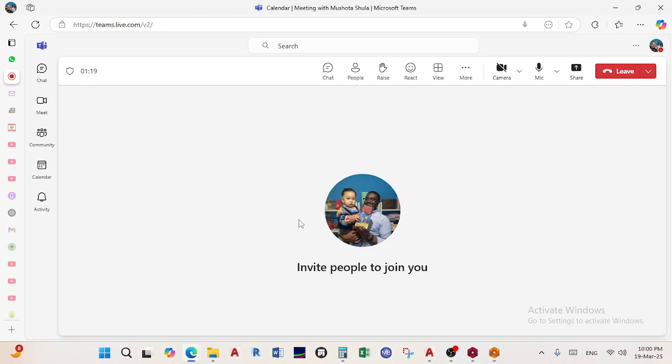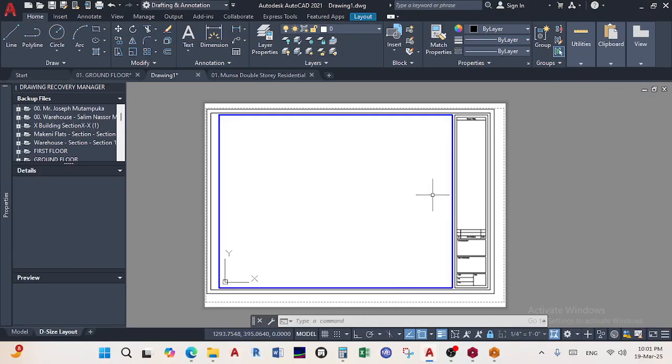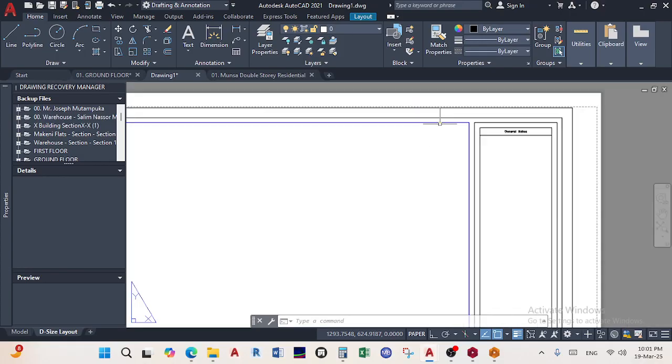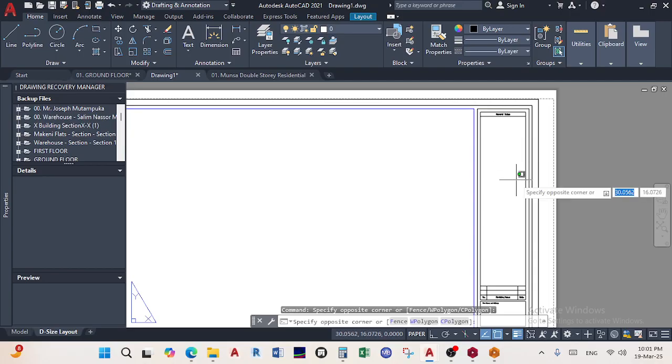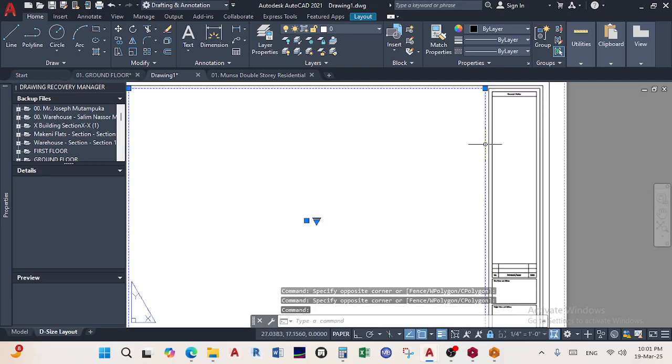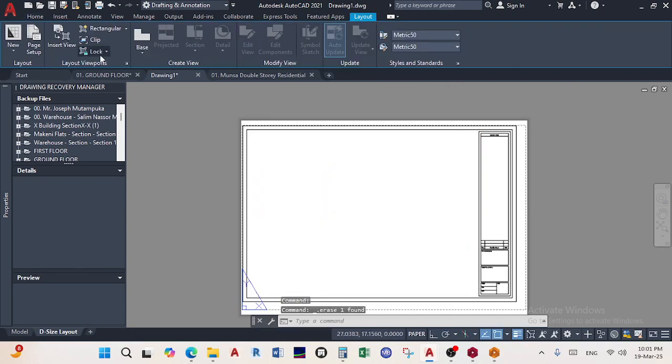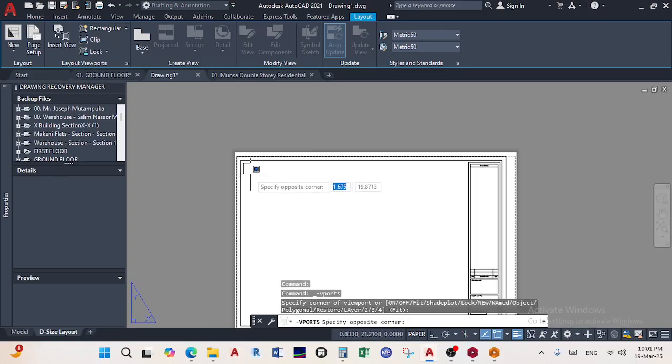Anyway, guys, it seems as if there's a problem. I'll continue. To finish up, you have to watch. So I'll show you how to put this template on an A1 sheet, and then I was explaining the differences between these other lines and this other one. For example, when you click here, nothing happens, but there's a designated viewport here that comes as a preset. If you like, you can delete it, but remember, go to viewport and then you can draw it, either a rectangular one or what, and you see it will give me the same designated color.